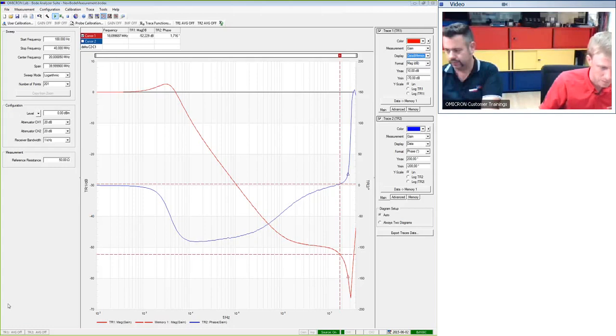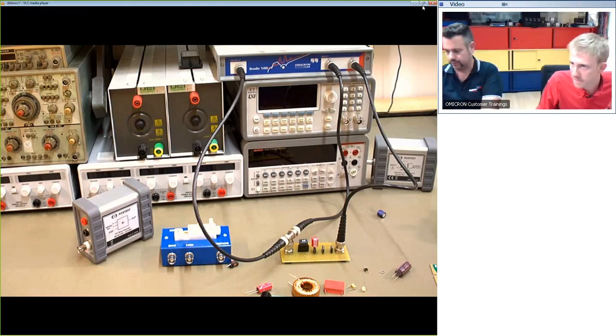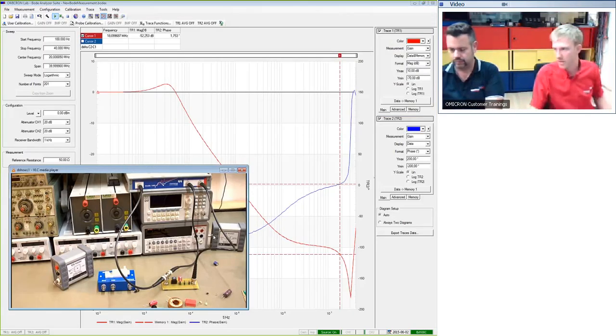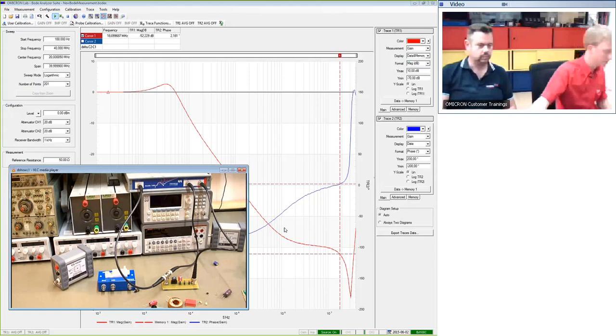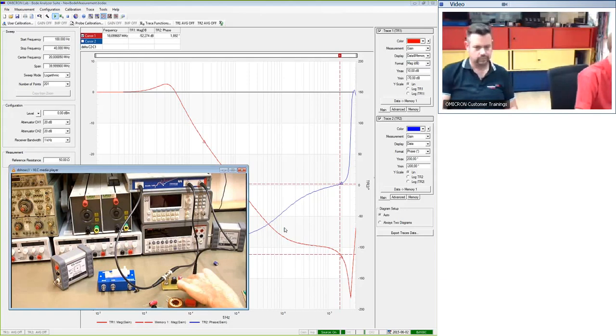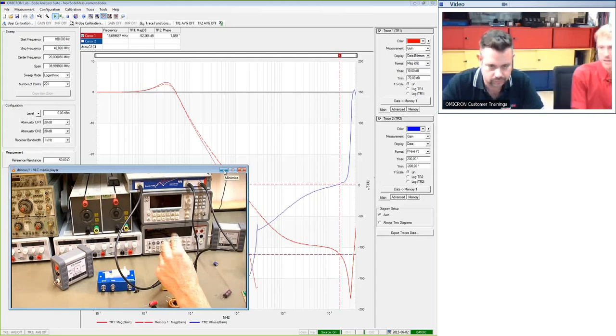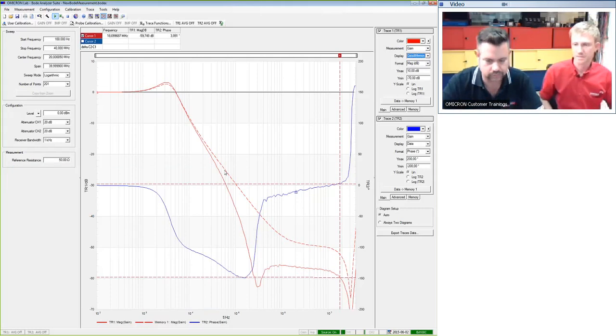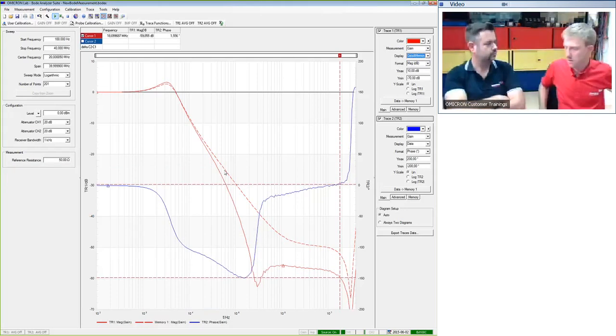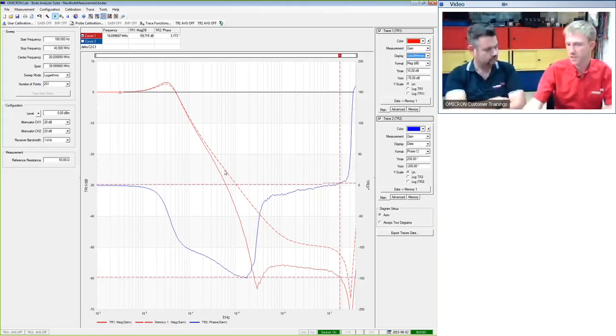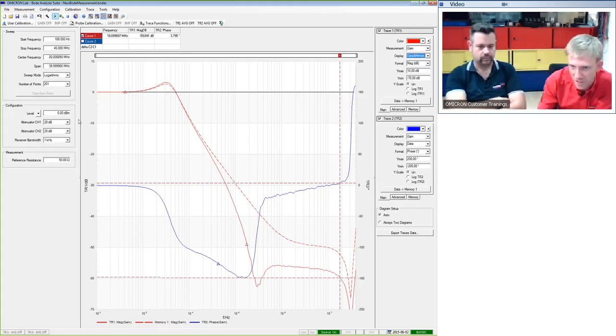Let's place on the camera here, and I do now add a 2 × 10 microfarad ceramic capacitor. So the total capacitance does not really change, but at higher frequencies, the curve changes dramatically.